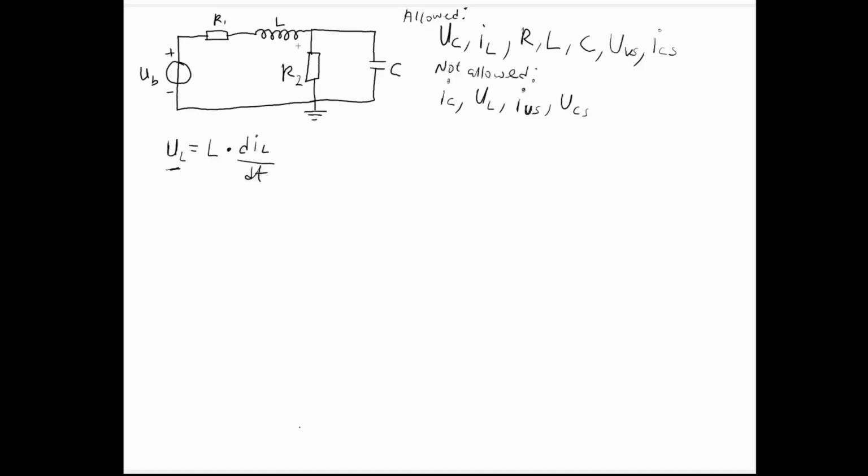So now this is the inductor. You look at the neighboring region around the inductor, because the inductor has two terminals. Because you have a voltage source here, a mesh current approach, like using the loop method with KVL, will be easier to make use of. What mesh does the inductor belong to? It belongs to the first mesh. This is the first mesh, this is the second mesh. So you make use of this mesh to form a structural equation.